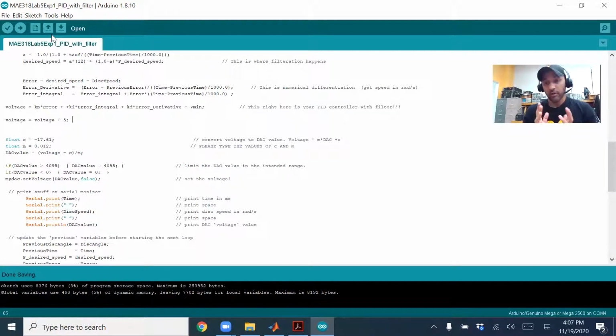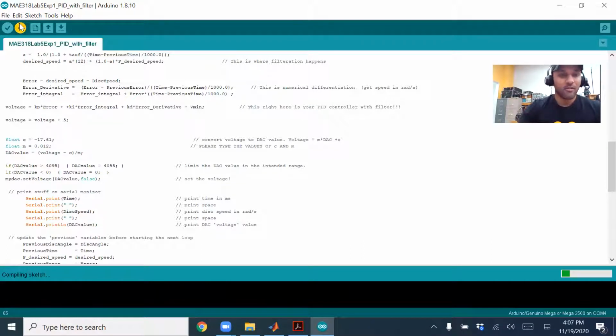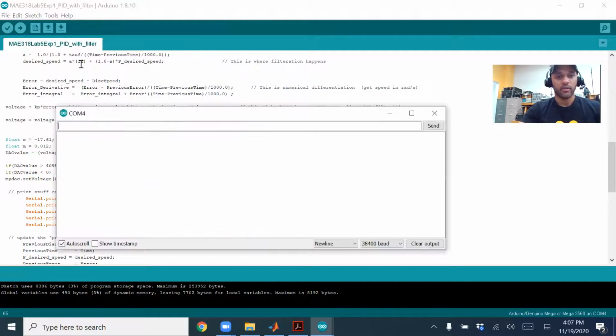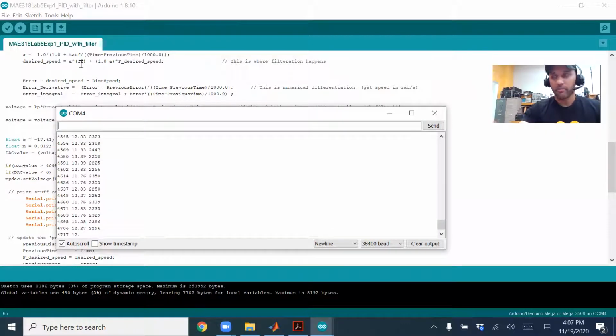We already know from theoretical analysis that having an integrator in control is going to get rid of the disturbance, but let's test it out in real life. Okay, so I'm going to plug my Arduino in and it's running because of the previous code. So we're going to just upload this. Let's see how it goes. Uploading, done uploading, serial monitor, 1, 2, 3, okay. Here we go, pretty quickly, it achieved the speed of 12. So despite the presence of this extra disturbance, the integral action helps you reject the disturbance.